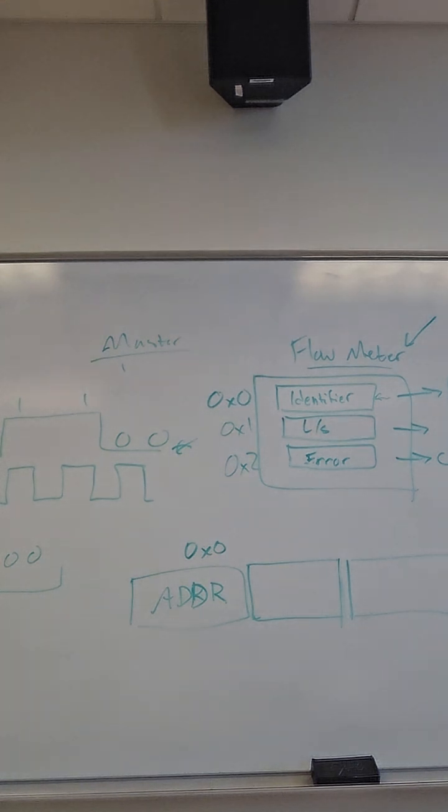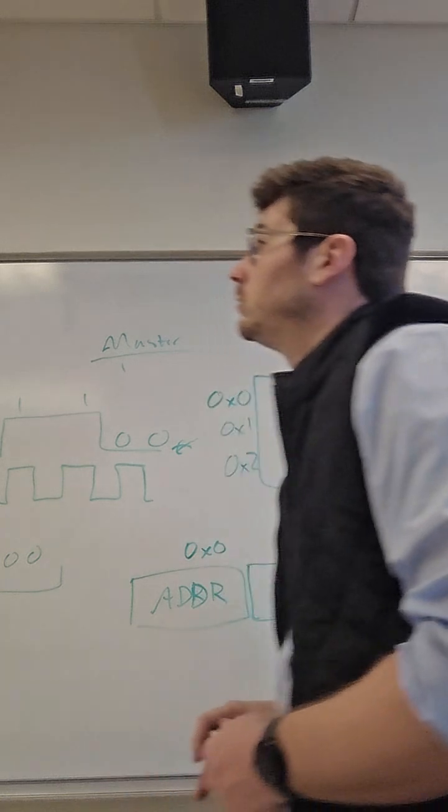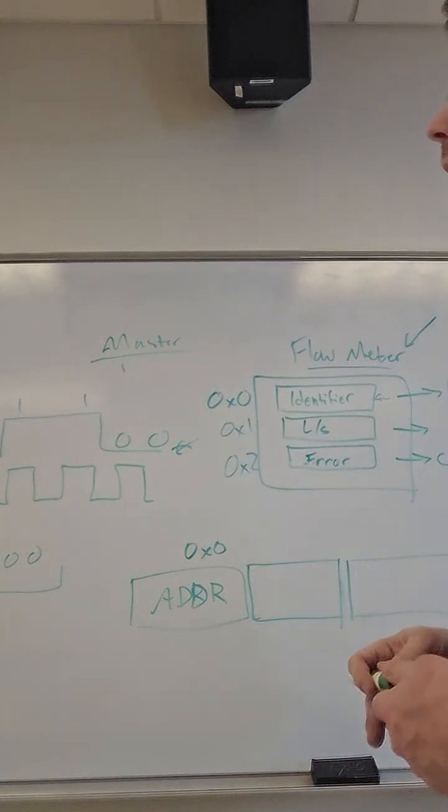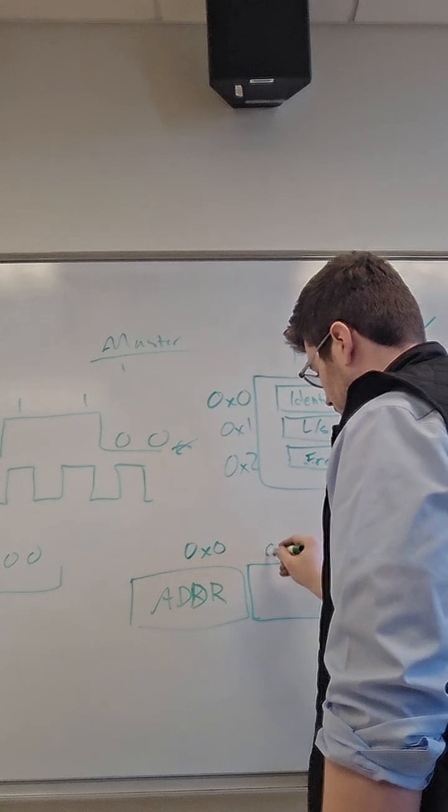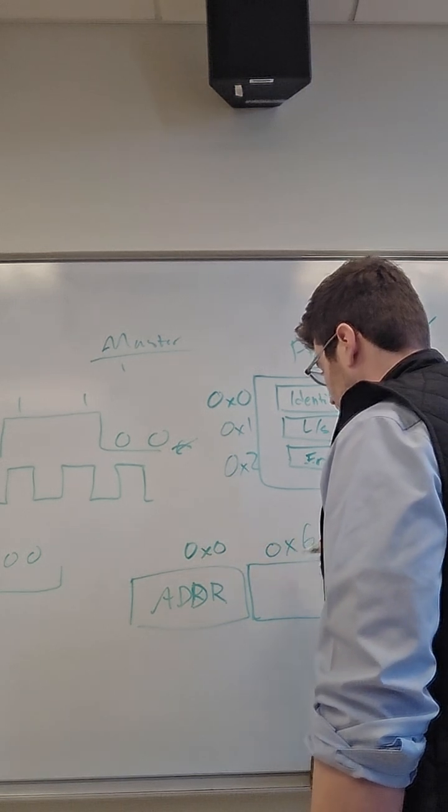Just like PLC, we have coils and contacts. That's what these registers are actually called, coils when we're storing information. So we can trigger different codes. For example, if we want to write a single register, to change the information that's inside of this register for whatever reason, we would write code 6, which means that this byte would be 0x6, right?